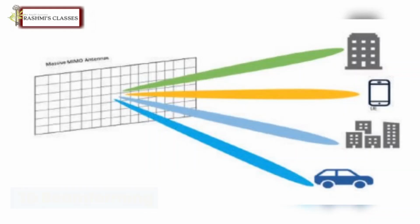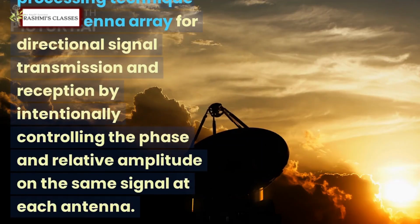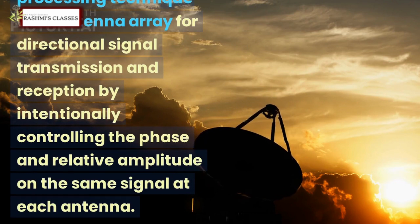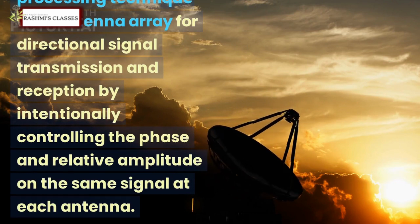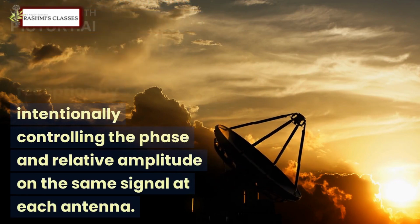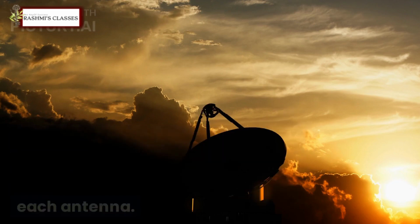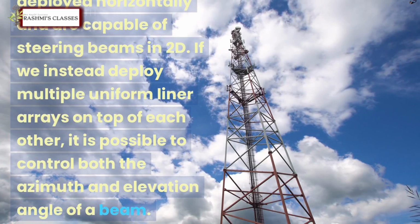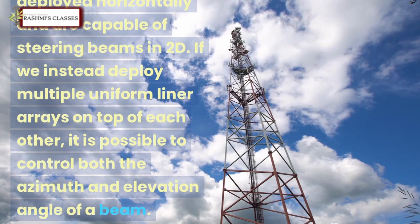3D beamforming. Beamforming is a spatial signal processing technique with an antenna array for directional signal transmission and reception by intentionally controlling the phase and relative amplitude of the same signal at each antenna. Contemporary multi-antenna base stations for cellular communications are equipped with 2 to 8 antennas which are deployed horizontally and are capable of steering beams in 2D.